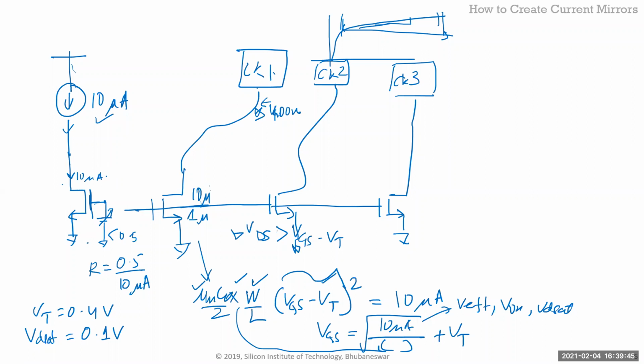That's the ideal current source. It's saying, I am not going to budge from 10 microamp. It doesn't matter what. You have to give me 10 microamps. The VGS is less than what is required. So what will it do? What will increase? Source is grounded. You can't move that. So you look at this curve here. It's the same VGS.